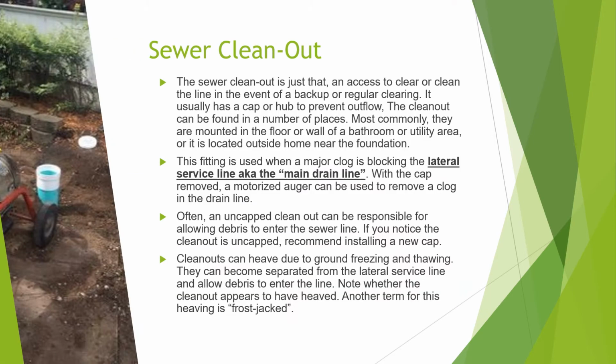The sewer cleanout. The sewer cleanout is just that, an access to clear or clean the line in the event of a backup or regular clearing. It usually has a cap or hub to prevent outflow. The cleanout can be found in a number of places. Most commonly, they are mounted in the floor or wall of a bathroom or utility area, or located outside the home near the foundation.